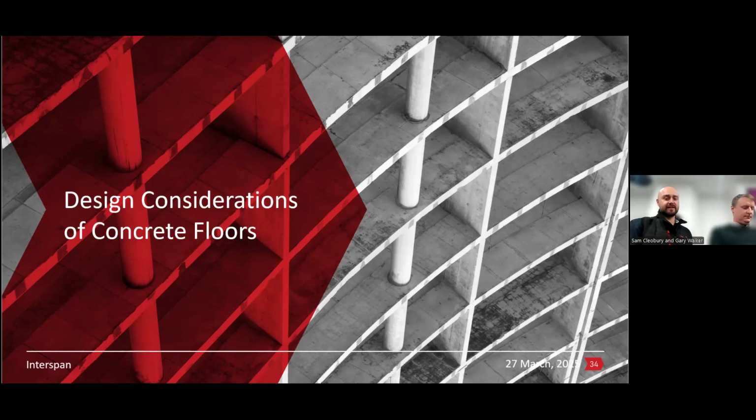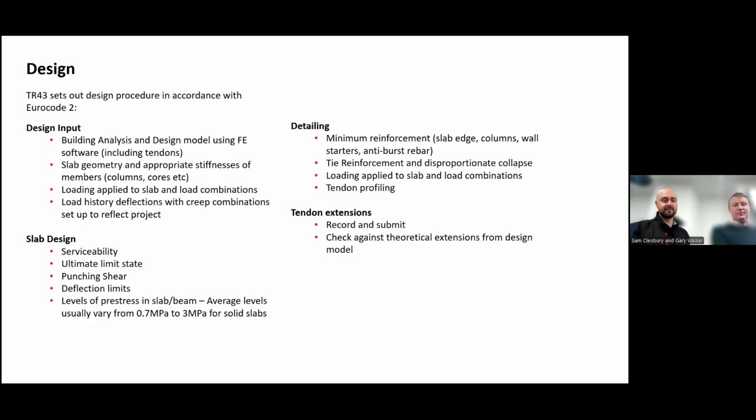So design, Gary, this is your bag. Yeah, so we'll do it quickly. The design of the PT elements is set out in Eurocode 2, and we use the Concrete Society's TR43 as its base guidance in the UK and Ireland. And we'll design very similar to the way that you design a conventional RC slab. We typically will use 3D FE software to analyze and design the PT slabs.